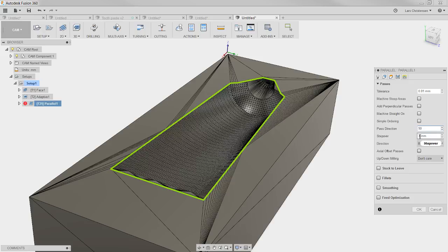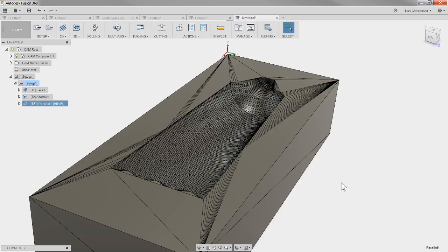The step over here is way too big. This is a roughing, and again, I've talked about this in other live streams, the step over. We can definitely revisit that. This is a roughing. I'm going to minimum do it at 0.75 millimeters, I think. Hit OK.